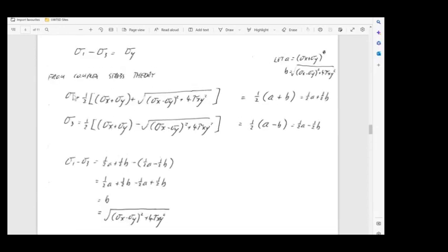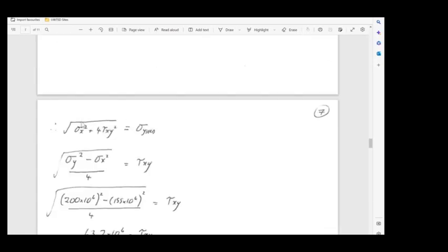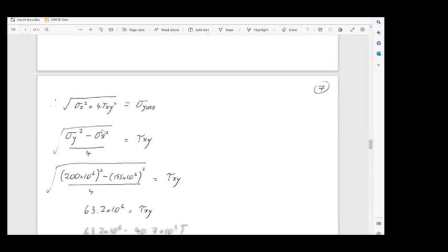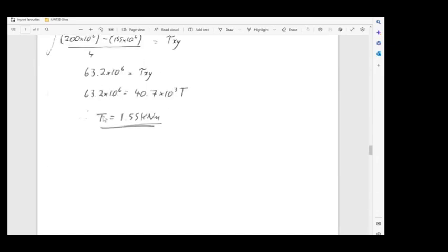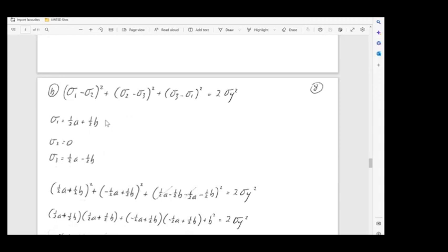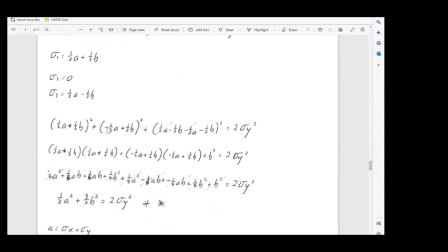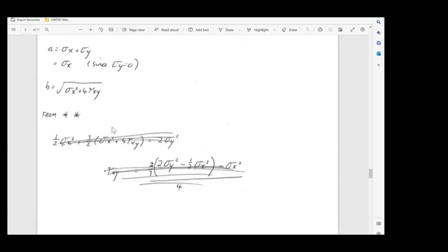Once we've got our principal stresses, we can then look at the failure criteria that we're asked to use. So, for example, our failure criteria might be this. So we calculate our failure criteria and therefore the torque which this shaft can use. So in this question, we're using the simple theory of elastic bending in order to calculate the principal stresses.